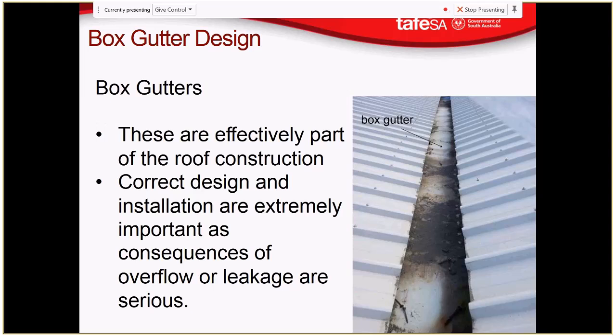Certainly, you can put a leaf guard, but some poorly installed leaf guards can be more hassle than they're worth. You need a continuous guard the whole length, because if you've got joined guards, they can fall in and cause you more hassle. You'd also want the guard to be removable for cleaning, because you still get dirt through a guard. In fact, I lived in a house with a box gutter, and it was getting blocked or impeded by the guarding in the box gutter as well.